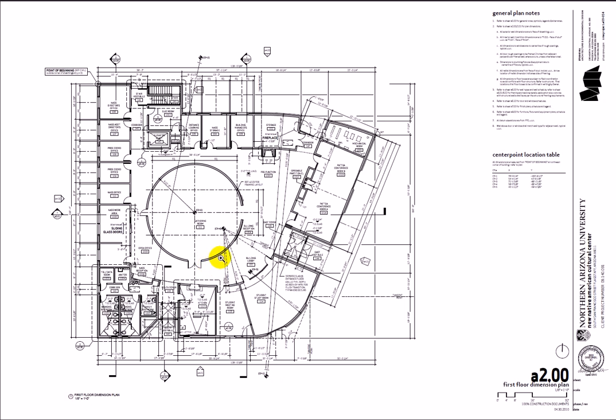So right now I'm seeing, okay, because the dimensions are all shown here on the architectural dimension plans, the structural engineer decided not to show them to make sure there was no confusion. That way there's only one source for dimensions. So this is where, unfortunately, the structural contractors, the foundation contractors, are going to have to come here to lay out their building.